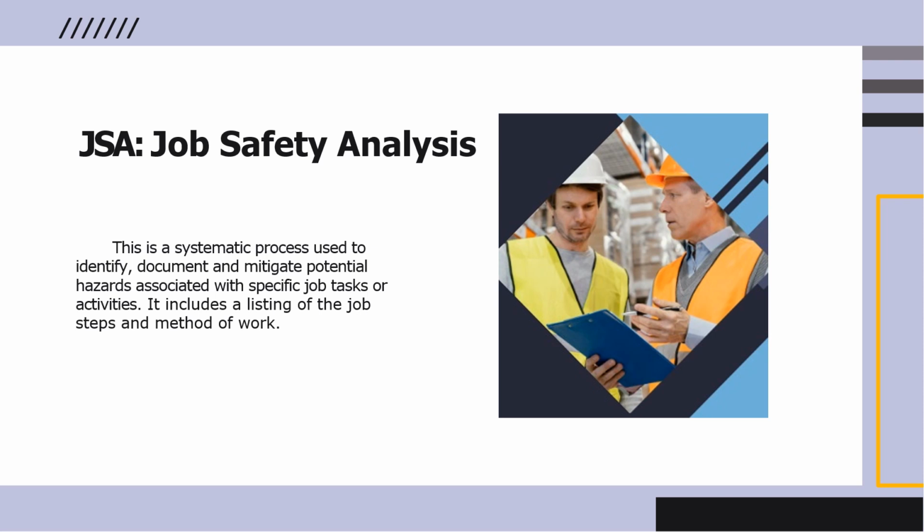JSA is job safety analysis. Most times prior to a group or a contractor carrying out a work, they need to spell out the kind of activities that will be done in that work, the different steps they are going to take, the methods they are going to apply, then the safety precautions on that job, and how they are going to mitigate any risk that might occur. All of this is documented and submitted prior to them carrying out any job in a facility. So that document has to be approved by safety personnel or those who are responsible prior to any job being carried out in a facility.